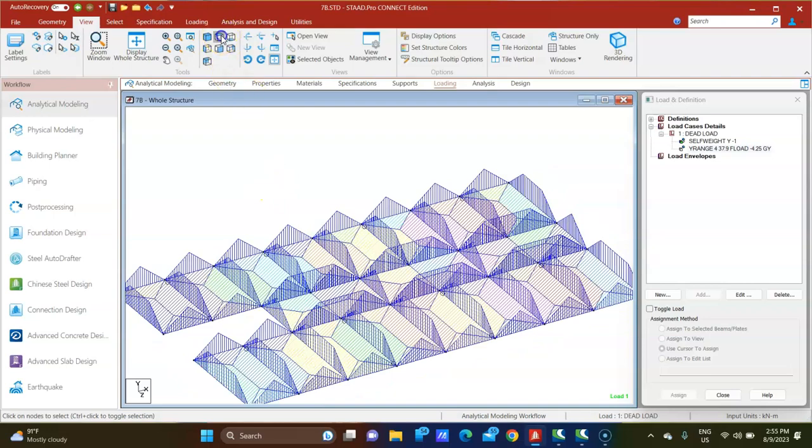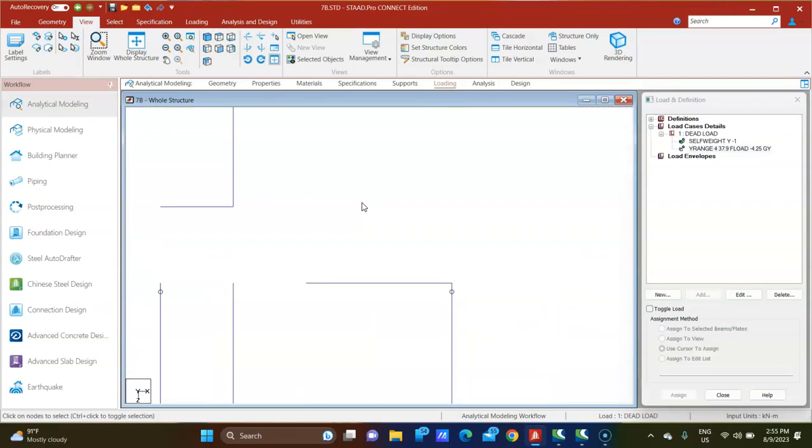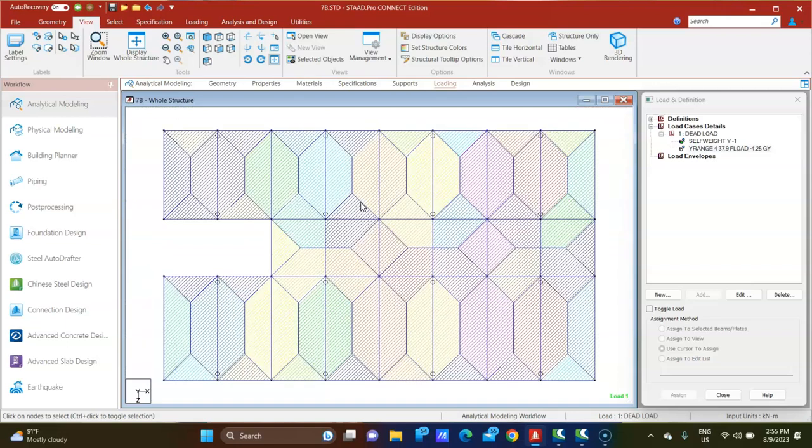And here an important thing: you see that on the left side, this panel load is not showing. Do you know why? Because of the staircase, right? But how will the software understand that there is a staircase? The interesting part is that this command will work only if the pressure intensity gets a closed loop.